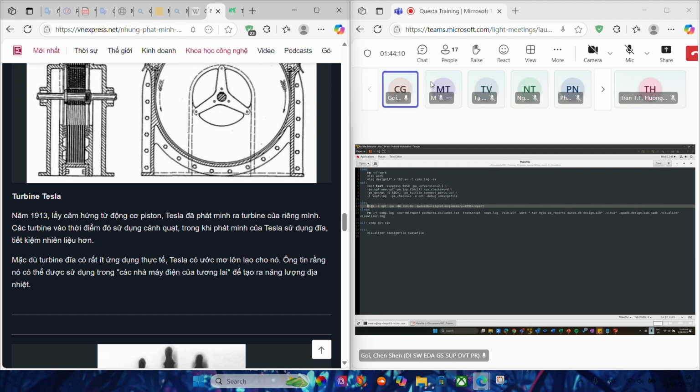At the sim stage, it's the same. We do vsim, and then console mode, your optimized DU name, -pa to enable the power aware verification flow, -do, and then we have a run.do file. We might have to see what it is doing here as well. Then we have our wave file, which will have all the wave information logged in qwave.db.